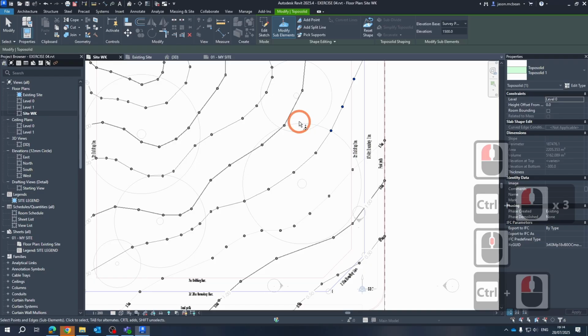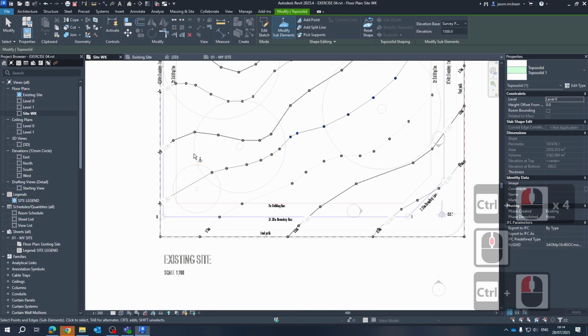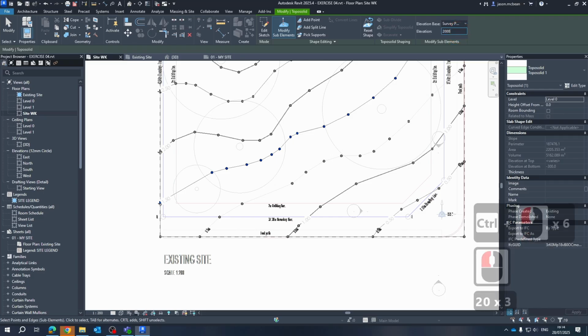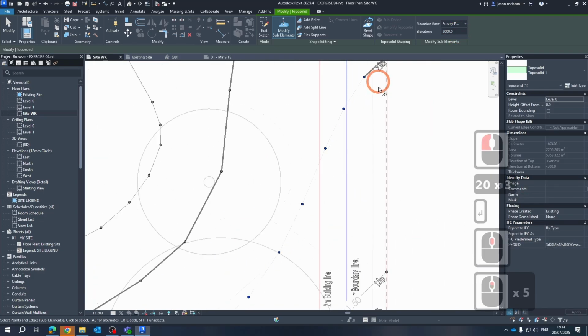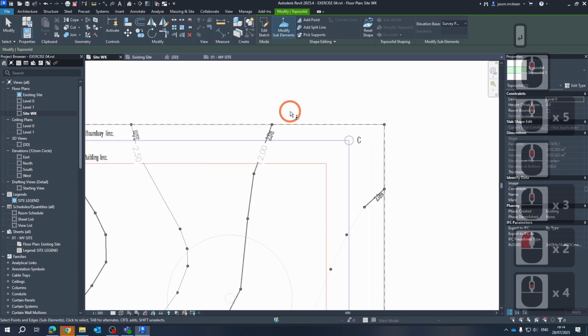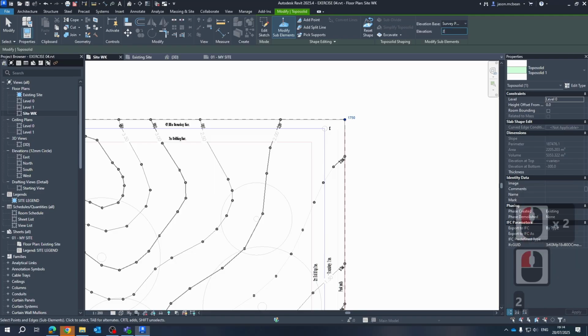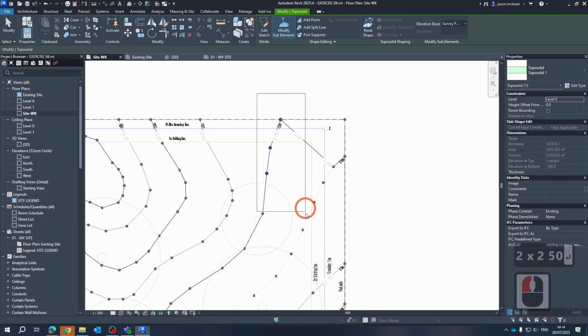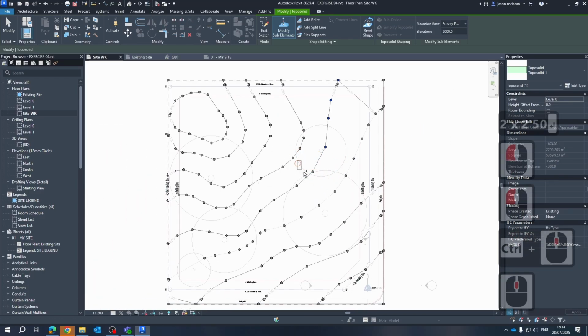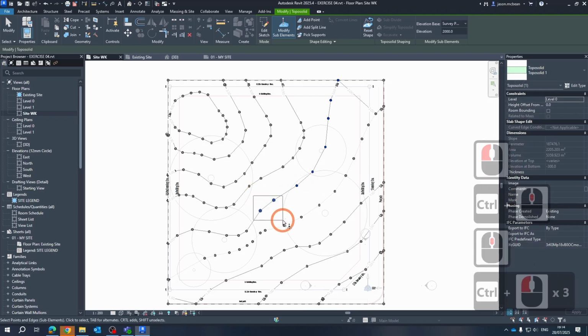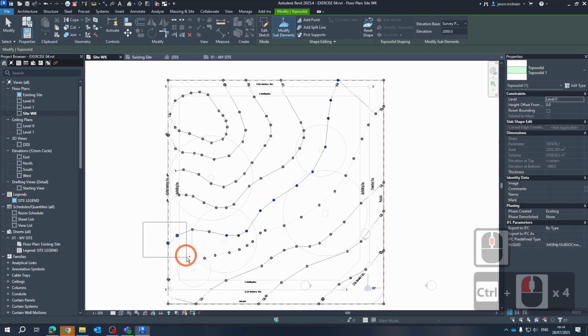Okay, so this will be our 2 meter. So hold the control down. But you noticed, very easy to fix. Okay, 2 meters, just make sure 2 meters. Now that would have been adjusted as well, so that would have been 2250. Okay, so now this will also have to become 2500. So that's very annoying. In theory, Revit should have picked up the correct information.